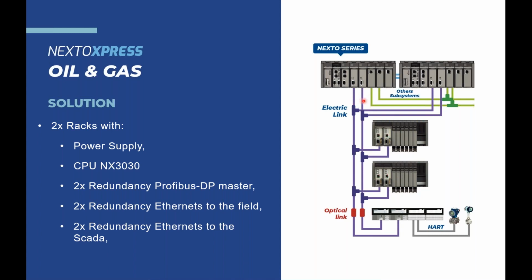When you have both networks active and both networks carrying all the information down, if we have the wire problem here, this remote here, the first one, will get all the information from network B. Since we keep network A running, if we have a fail on this module here, this remote will get the information from network A. So you keep control of all of the process.